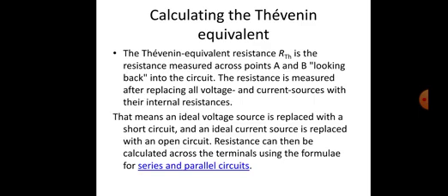The power dissipation of the Thevenin equivalent is not necessarily identical to the power dissipation of the real system. However, the power dissipated by an external resistor between the two output terminals is the same regardless of how the internal circuit is implemented.